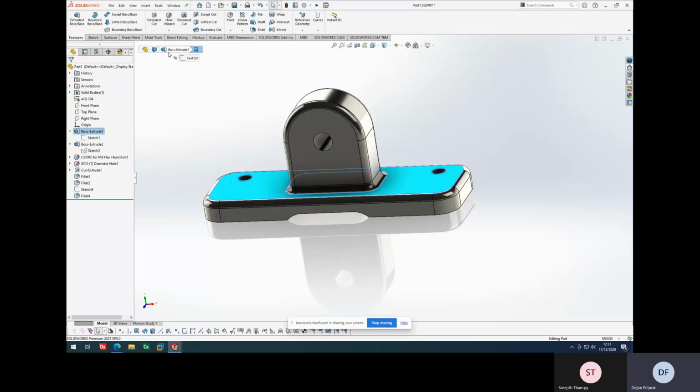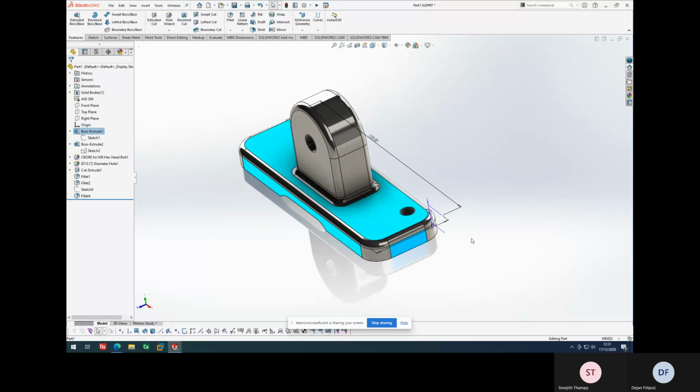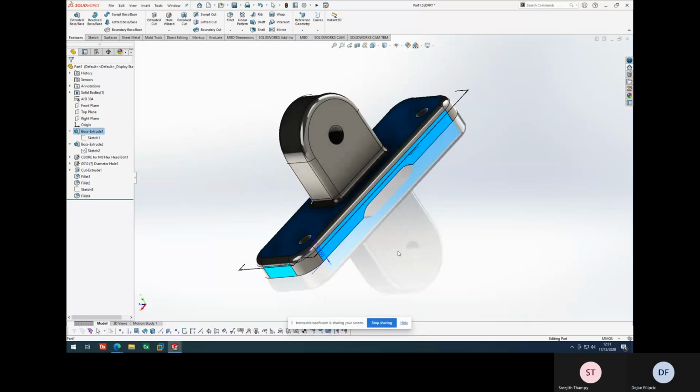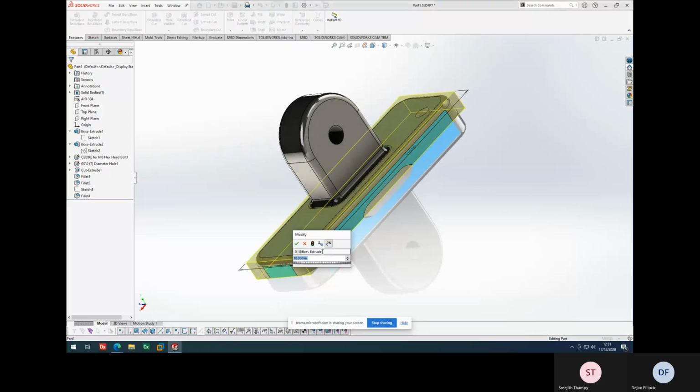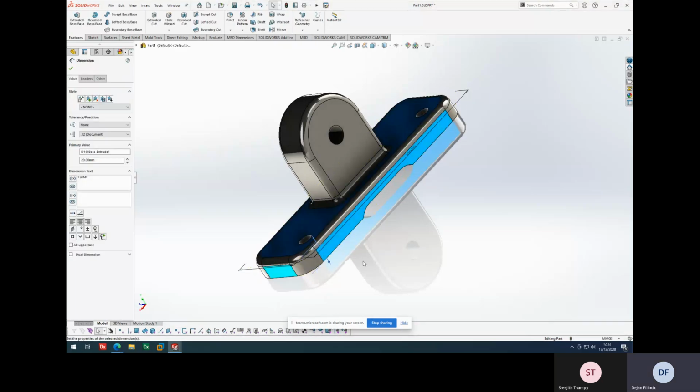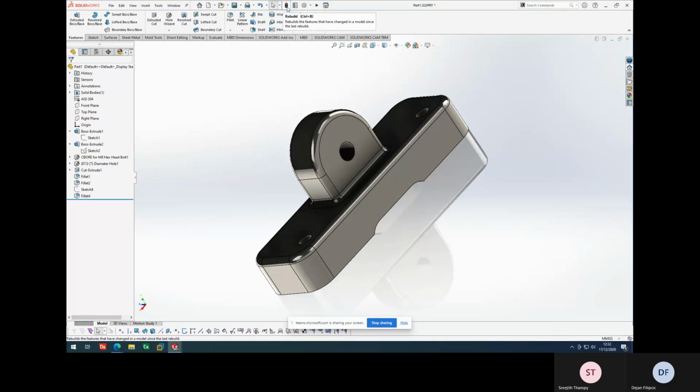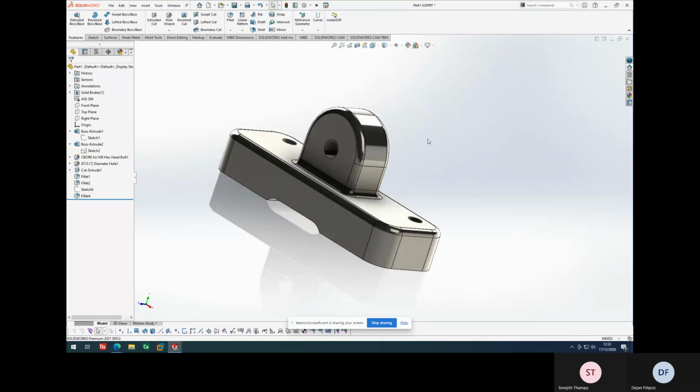So you can always see exactly what made that happen, and you can go down the steps, in different levels, down to the basic feature that generated that, which was a section or a sketch or whatever it was. And another thing: you have created this extrusion. If you double click on that body, it will show the dimensions that are related to it. So I don't even go back to the feature and edit it. I can directly change it. It is 10 here. I want to make it 20. From here, I can make it 20 and update it. Accordingly, there will be a change.